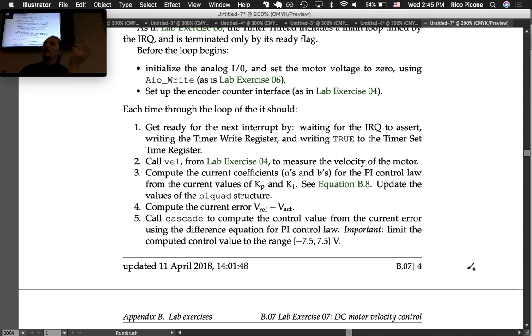So remember, just like last time, if it says to do 50 volts, we can't actually put it out, and it would just put out the 7.5. But if we limit this in the code, then the values that we dump out and the previous values will be correct. It computes based on the previous input, so it won't be an incorrect value. It won't have actually put in 50 volts. So you don't want it to think it put in 50 volts.